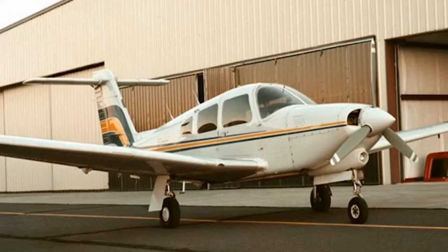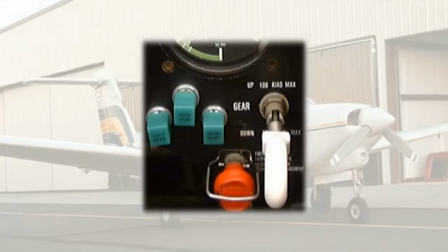Retractable landing gear is also provided with mechanical locks to ensure that each undercarriage is locked securely in the retracted and extended positions, devices to indicate to the crew the position of each undercarriage, and a means by which the landing gear can be extended in the event of a failure of the power source. In addition, a system is provided to prevent retraction of the landing gear with the aircraft on the ground, and to guard against landing with the landing gear retracted.